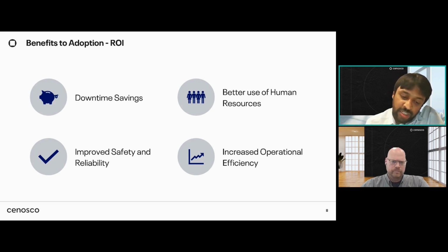What will change is the way we perform probability of failure assessments. Today, we're just taking a corrosion rate, maybe carried out on the back of an inspection 2 years before, and we're using it as part of a risk assessment to drive our criticality values.